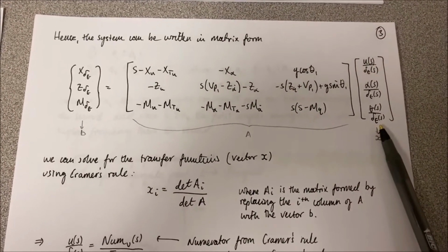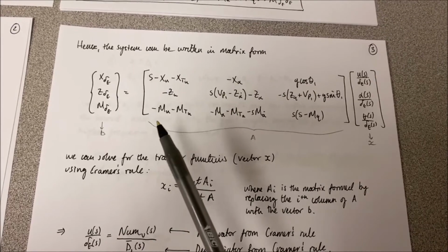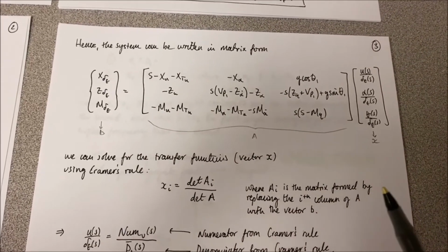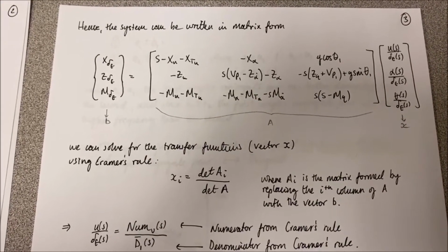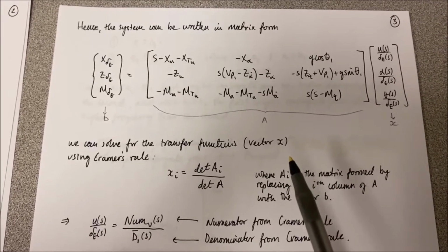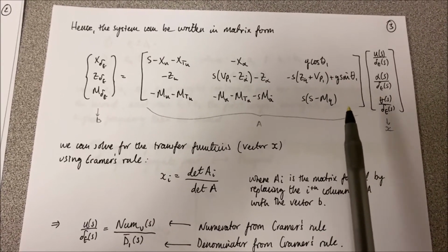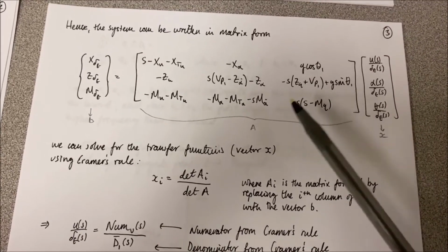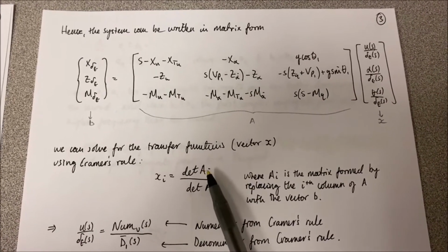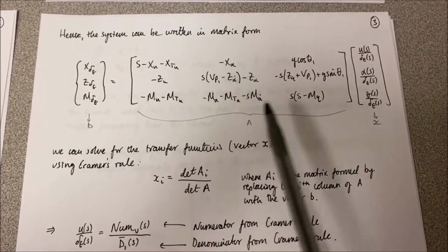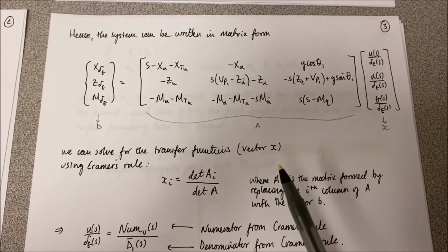These are the transfer functions, right? These are the expressions which multiply those transfer functions, and these are our known inputs, the elevator deflection angles, right? So there's a reasonably straightforward solution to this called Cramer's rule, which we can get something like MATLAB to solve for us, right? Basically what this does is it solves for the transfer functions, these ones which we're trying to find ultimately, by applying this formula where we find the determinant of this 3 by 3 matrix here, which is not trivial if you're doing it by hand, but a computational tool will sort that out for us, no problem.